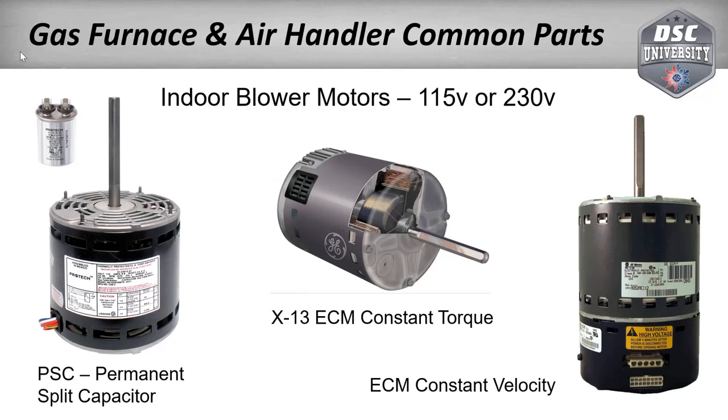Probably one of the biggest features is they have different controls and different settings where, when you're in the air conditioning mode, if the humidity is too high in the house, you can actually make the blower motor slow down a little bit. And when that blower motor slows down a little bit, it moves the air slower across the coil, takes more moisture out of the air, so it dehumidifies better. Besides increasing efficiency because of the way they work and the way they move the air better, they actually increase the efficiency rating on the outdoor unit, but then you also get the benefit of the better humidity control inside. So we've got the PSCs, our X13s or constant torques, and then the full ECM, which they call a constant velocity motor. So you have your good, your better, and your best.